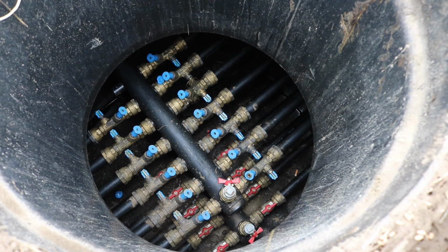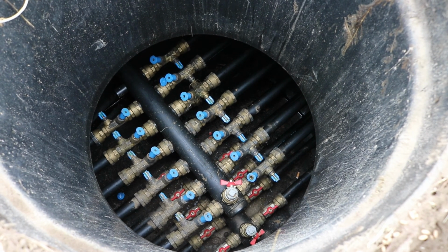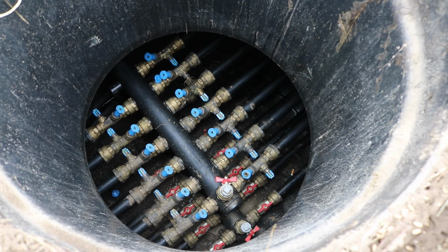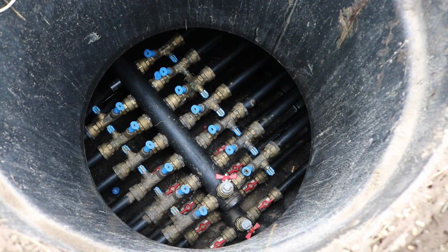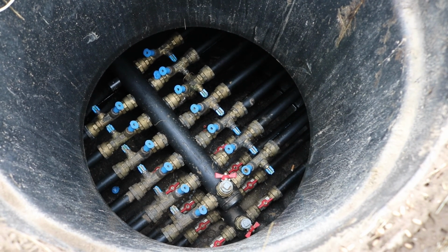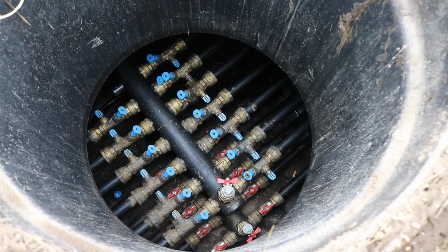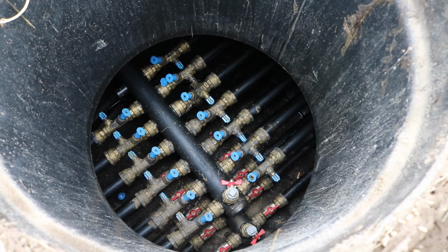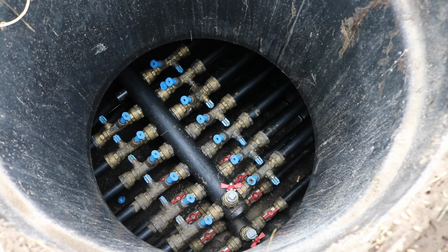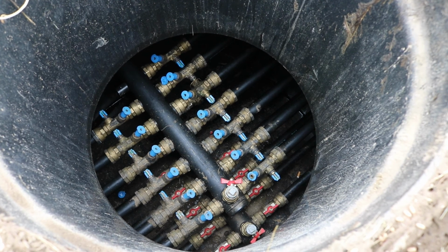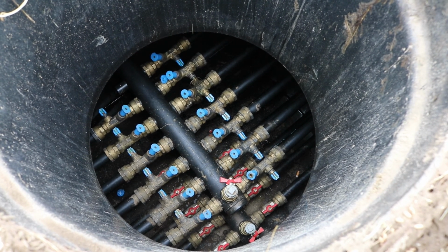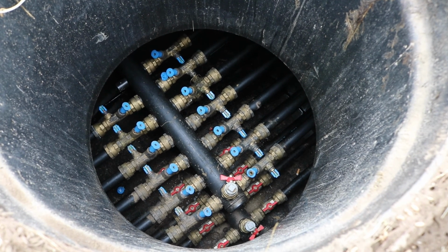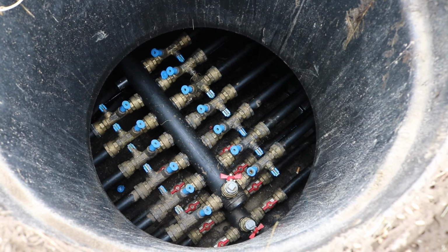They go all the way inside, 80 meters low into the ground, and the fluid inside transfers heat from the ground to itself, heating up. Then we use this heated up fluid as a lower source of the heat pumps. We have 53 of these vertical U-tubes to take energy from the ground.